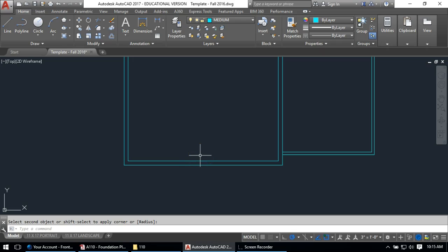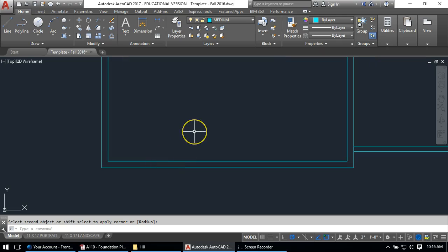But we've got, let's see, those dimensions are a bit hard to read on this, aren't they? It's 1 foot. Yeah, so it looks like there'll be an inset here that looks like it's 13 feet over and 1 foot back. Again, there's some brick detail I'll talk about when we get to that point, but I'm just getting the overall shape. So I'm going to start just by drawing a guideline down and offsetting this 13 feet to here.